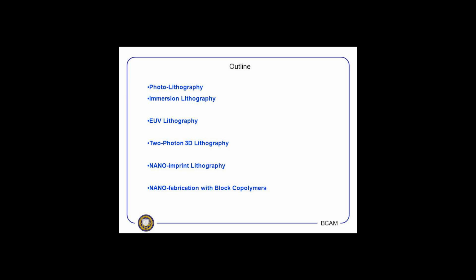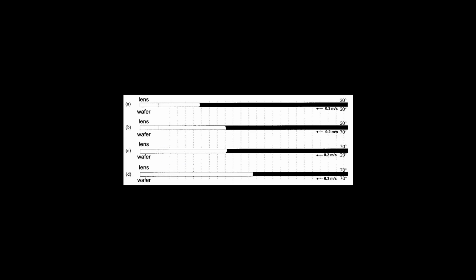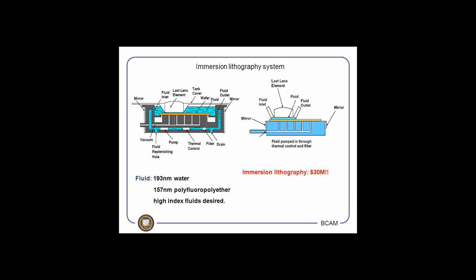Benefits of immersion lithography. The ability to resolve features in optical lithography is directly related to the numerical aperture of the imaging equipment. The numerical aperture is the sine of the maximum refraction angle multiplied by the refractive index of the medium through which the light travels. The lenses in the highest resolution dry photolithography scanners focus light in a cone whose boundary is nearly parallel to the wafer surface, as it is impossible to increase resolution by further refraction.